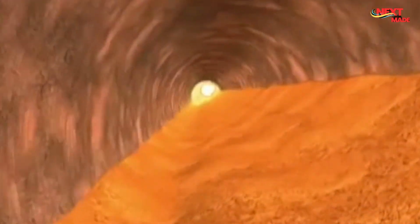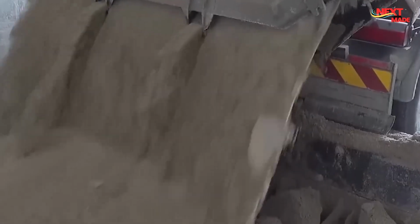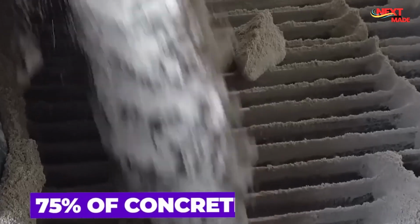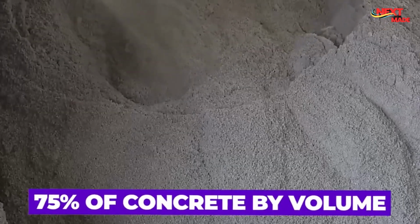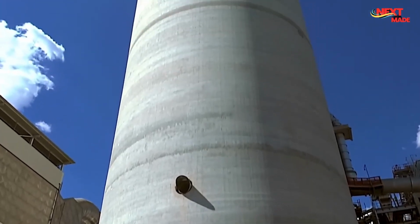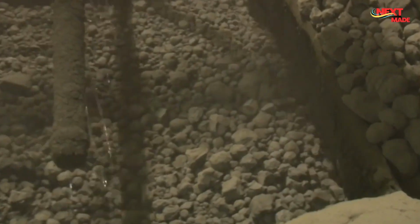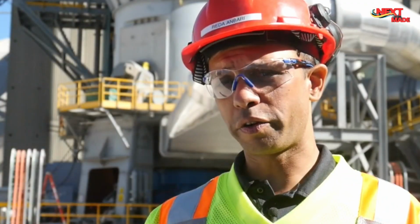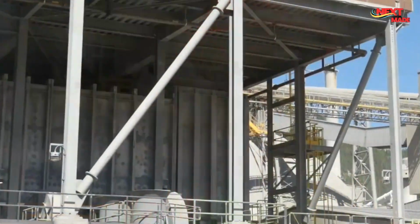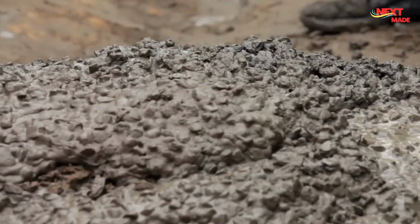Now is a great time to talk about the hidden stars of concrete manufacture, the admixtures. These chemicals offer a range of advantages and may be added to concrete to improve its properties. Plasticizers give the concrete greater workability, which refers to its ability to be easily molded and placed without segregation or excessive bleeding of water, allowing it to reach congested areas. Accelerators or retarders are another type of admixture that speed up or slow down the setting time for concrete. Due to the fact that concrete cracks under tension, many chemical additives have been developed to increase the tensile strength of concrete. Concrete may also be strengthened by using fibers made of stainless steel, glass, and carbon.